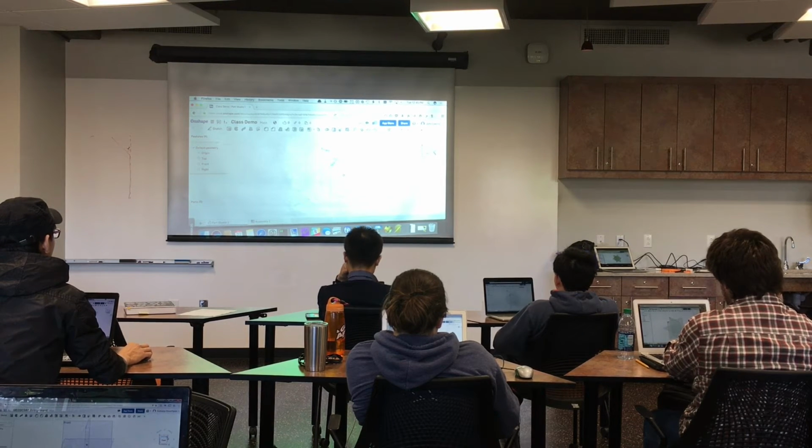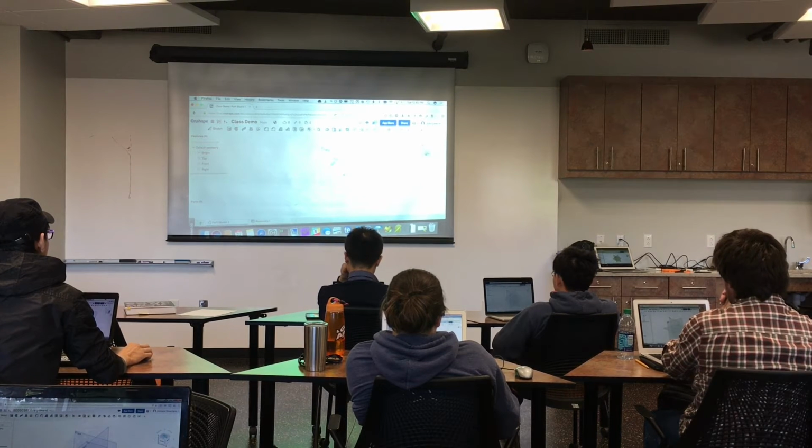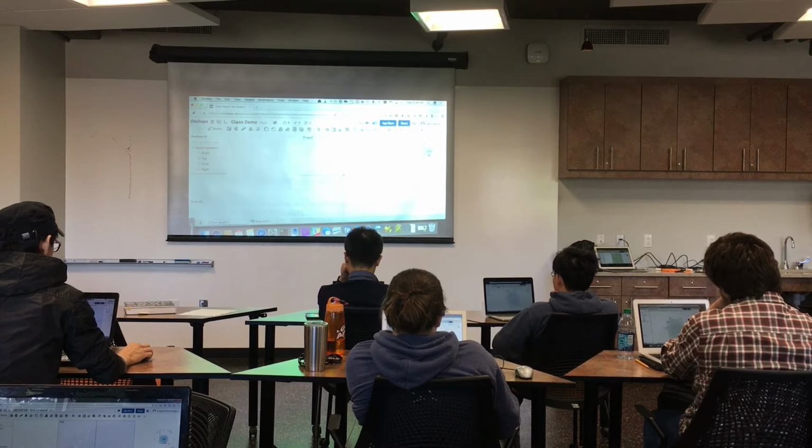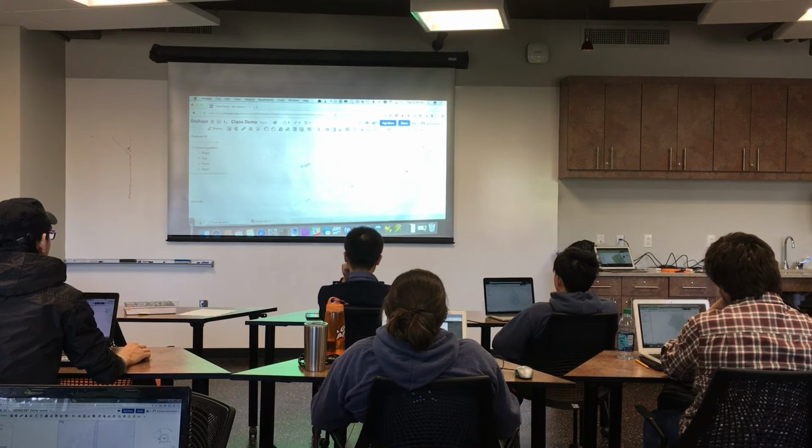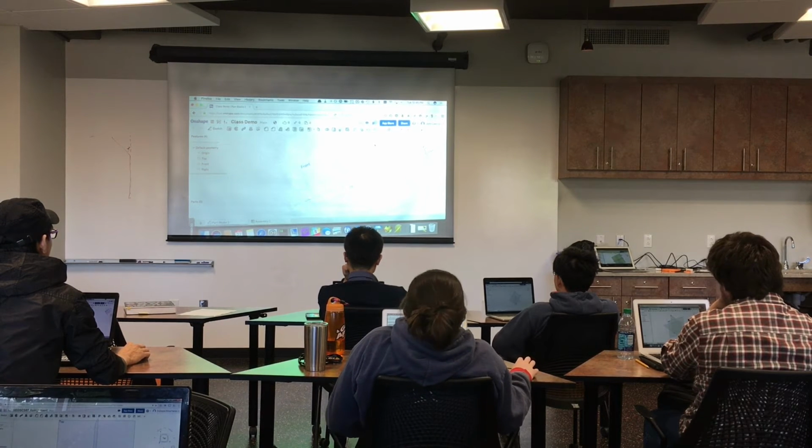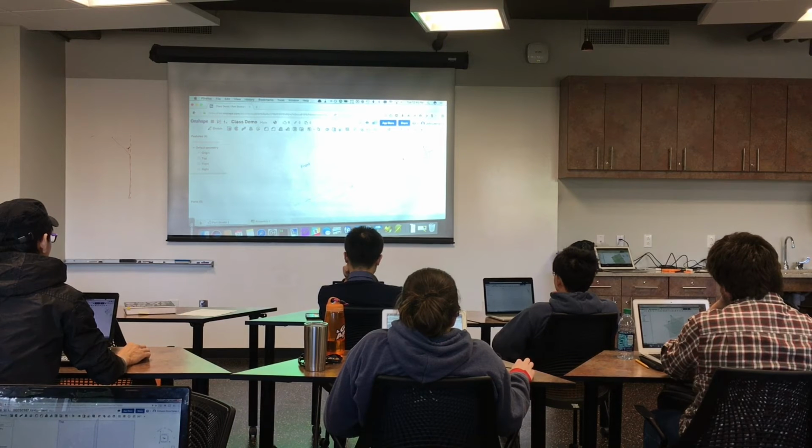If you click on any of these faces, you instantly get to that view. Like if I want to view the top, or this corner view, or front view, or however you want to view your part. If you hold your right mouse button down and drag, you rotate. If you hold the left mouse button down and drag, you select. And you'll notice that if I drag to the right, it's blue, and if I drag to the left, it's orange. This determines whether you have to have just the edge of a part in to have it selected, or if you have to have the entire thing included. I'll show you how that works in a second.